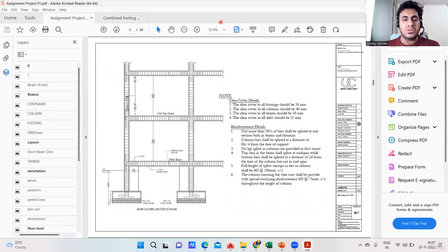In this way, you can see up to here you have taken the column height, isn't it? This is your plinth beam. Up to here you have taken. So how many portions are left out? Again, you should take this column height and this column height, and then the last is a parapet. I feel this is a small parapet which will come. It's okay, you can take the parapet also, just see which columns are going to the top, and there you can take.